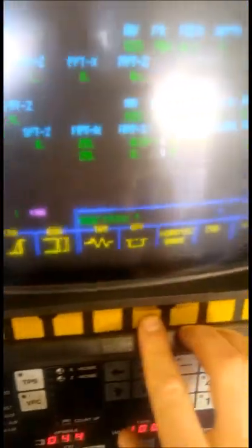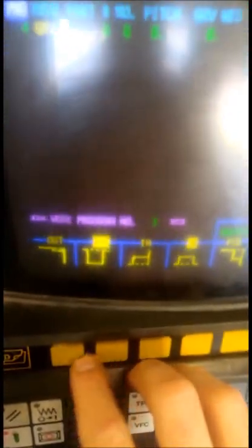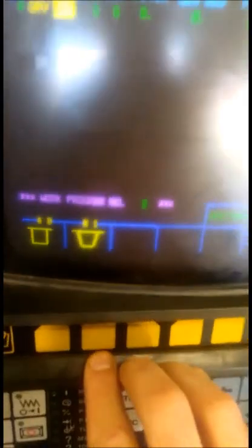Then the next operation we're going to do is a groove operation. Two different types of groove as well. We've got out, out, same as what I said with the bar work. So this is in from the end, so it's a bar out, a groove out. And there's two different types of grooving styles. There's 0 and 1. So 0 is just a straight groove and 1's supposed to be a trapezoid groove. But I use 1 all the time for my straight grooves as well, because one of them measures from one side of the tool, whereas the other measures from the other side.